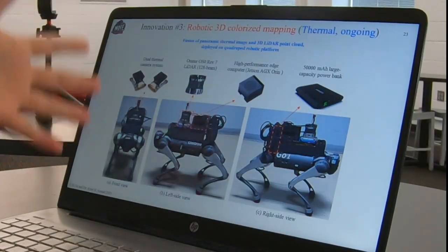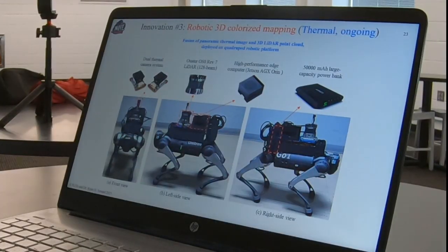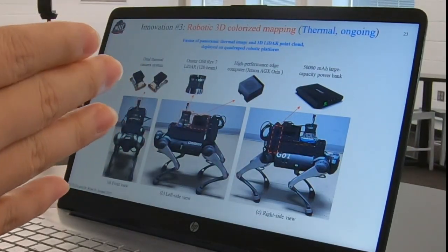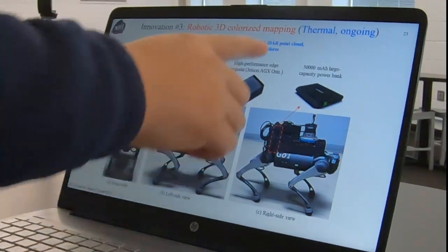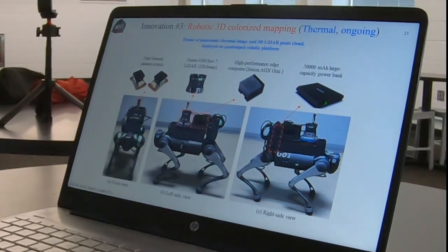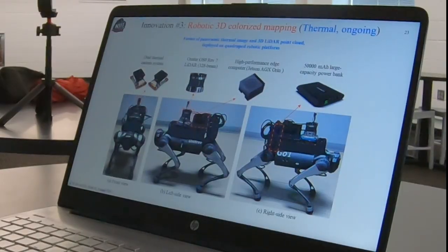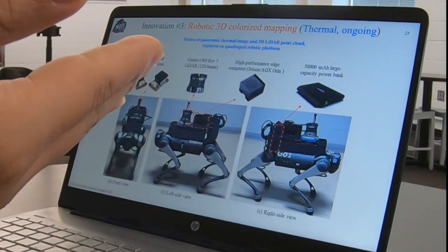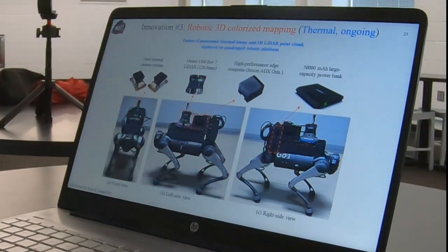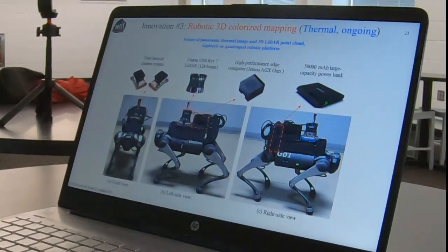Another thing: the first thing is RGB cameras. We can only deal with surface defects. But what about the stuff behind the wall or within the wall? So there's another idea, thermography. Thermal imaging can tell us about subsurface issues, let's say damaged insulation in the wall. If we just look at the surface of the wall, we cannot identify that, but thermal imaging would allow us to.